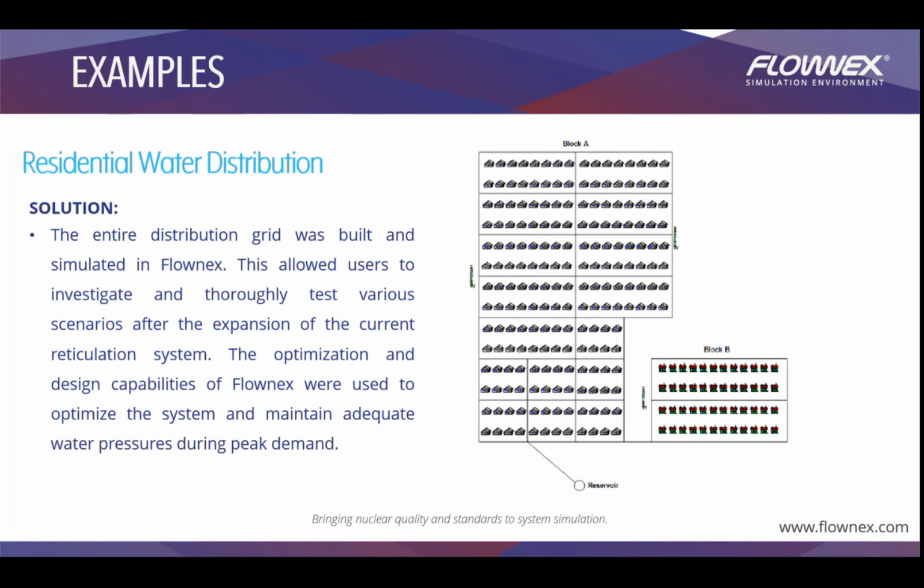So we'll notice that at some time of the day we'll need more water, for example, in the morning and at night, where people will go to work and they'll need to bath or shower, then we'll know that the water demand will increase. Then we had to make sure that we meet those water demands, and you could do those simulations in Flownex as well to see whether we'll meet the water demands or not.